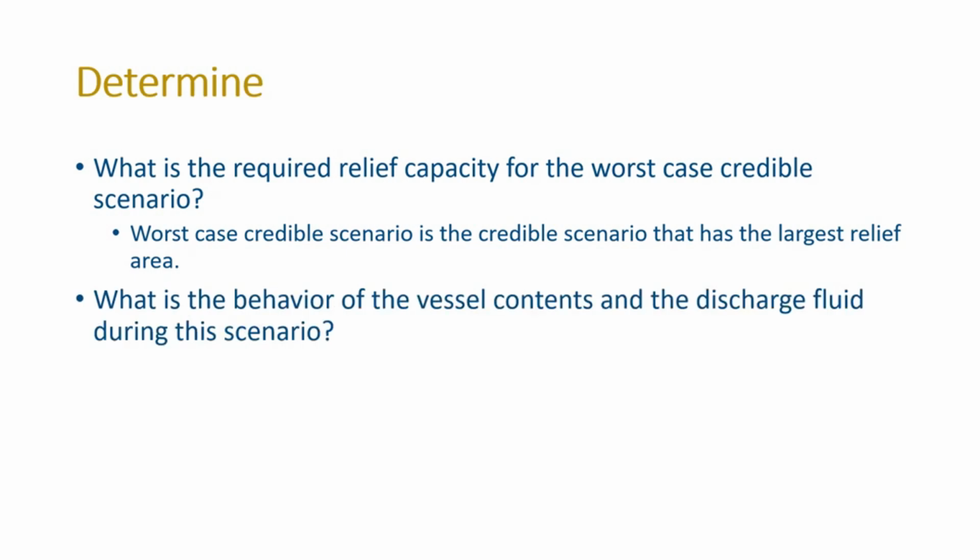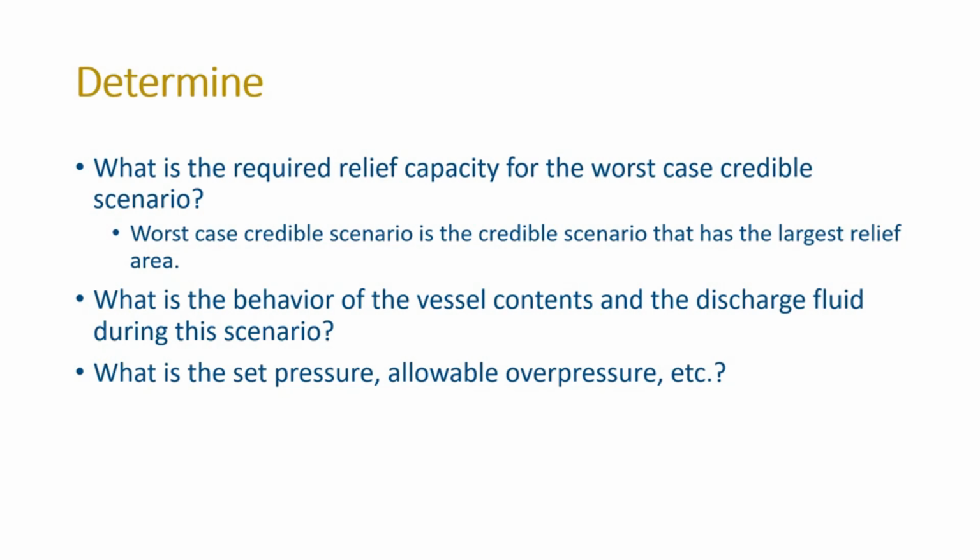You also want to determine what is the behavior of the vessel contents and the discharge fluid during this worst case credible scenario. You want to determine what the set pressure is, the allowable overpressure, and all of those other pressure set points that we defined earlier on in the week.